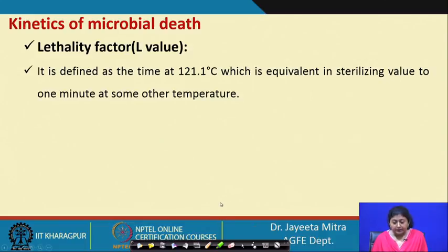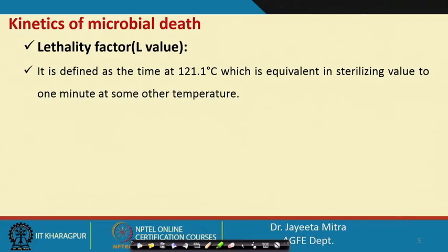That means, if we want to destroy the number of microorganisms at any temperature in such a ratio, that is log of N0 by N, so that the process time at that temperature is 1 minute only, the same microbial destruction if we want to cause at 121 degree Celsius, then this time required at 121 degree Celsius will be termed as the lethality factor.